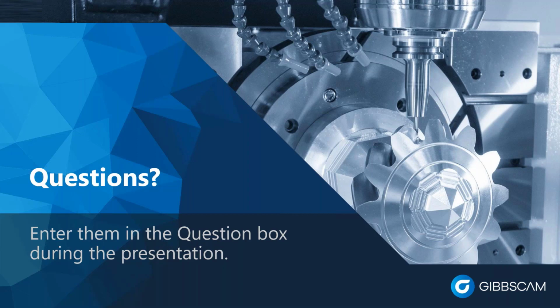Same as in 4-axis. Sometimes you say, well, I don't need the 5-axis module because I only have a 4-axis mill. Well, the 5-axis module works very well in 4-axis. Again, you just lock out one of the rotary axes and you have a very effective 4-axis simultaneous machining toolpath engine there. And of course, it supports off-center milling, which it would have to do to be effective. And it will also support a mill turn center, like an Integrex, correct? Absolutely, yeah, really well in the Integrex.